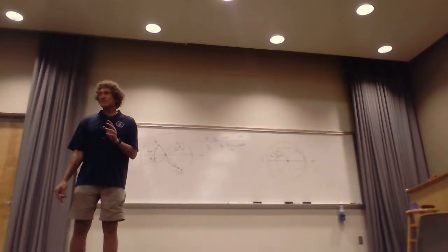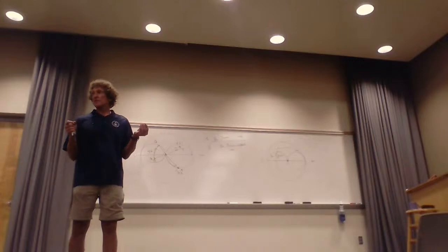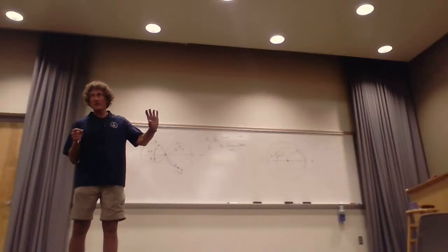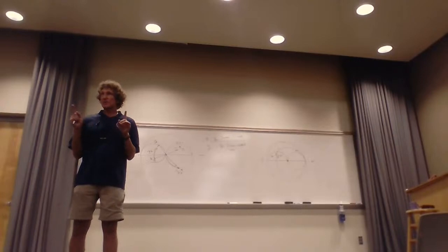Most of the time in series, an inductor is great. The reason is that there's often DC biasing in circuitry. Often when you do this L section matching, it may be something that goes in parallel with an output antenna, but it might have a circuit next to it that requires a DC offset. So I always allow the inductors to go in series, and Whitworth's book brings that out, because an inductor has zero impedance to a DC current.